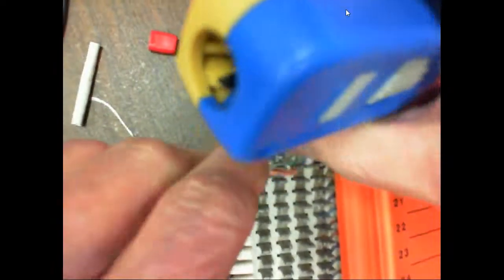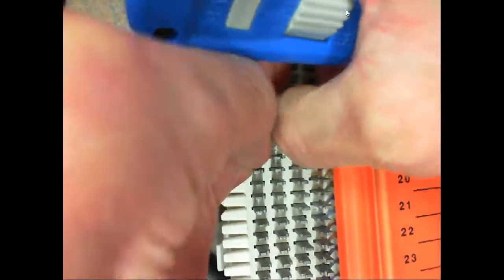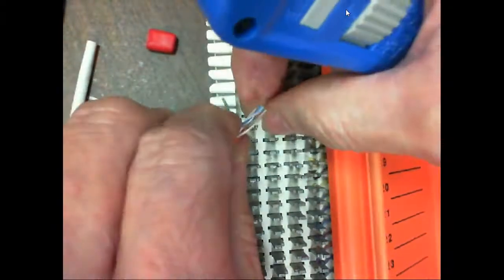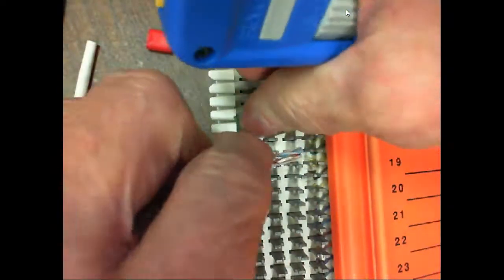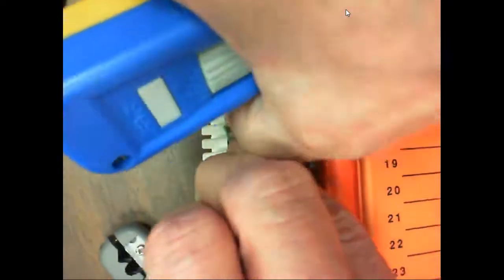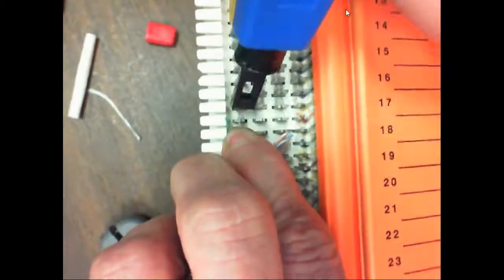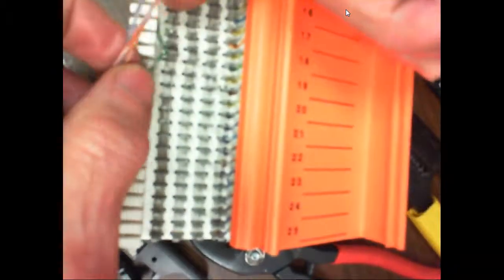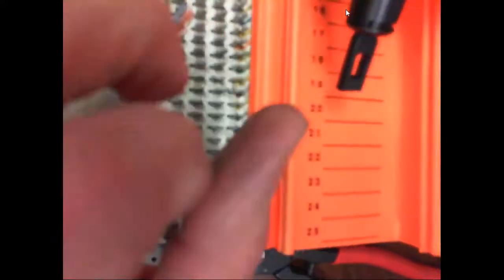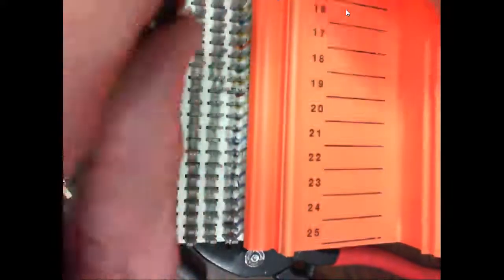We got to get it into the groove, Rich. So we started into the groove, right? And then we come in, put the blade away from the conductor toward the end that's out. We push it down, and we hear a snap like that, and it automatically does what? Pushes it down into the block and also cuts off the end that extends out.